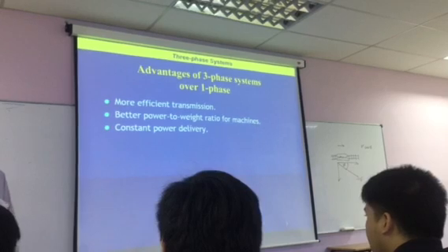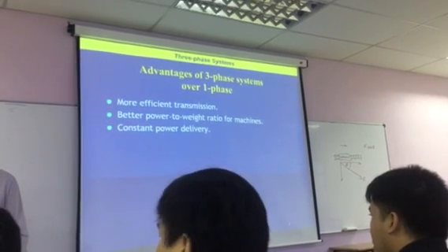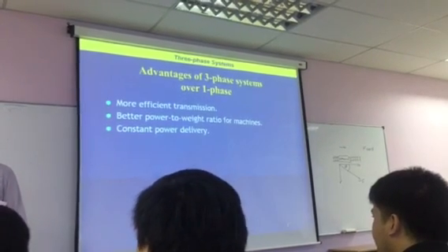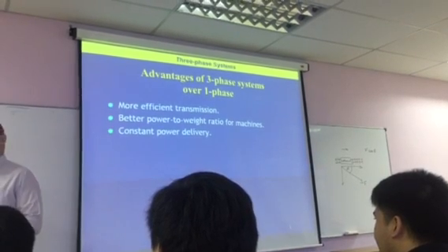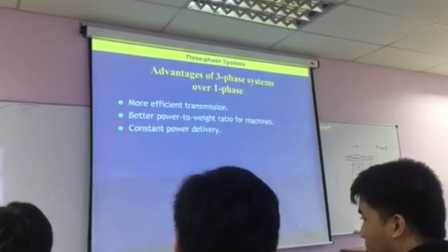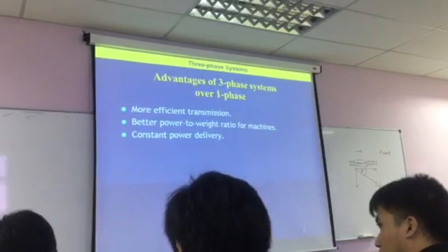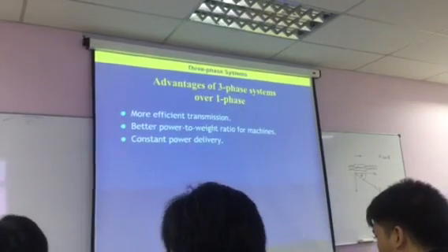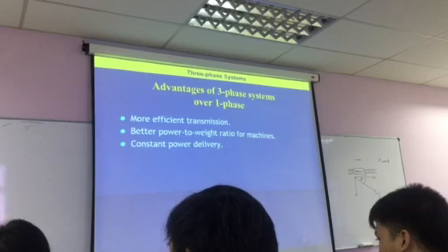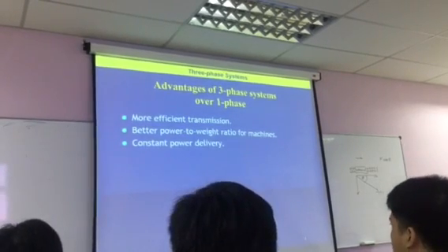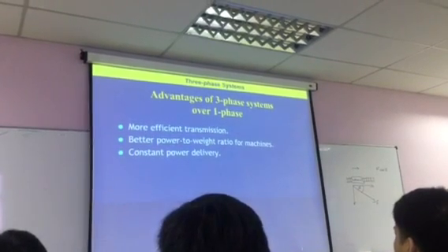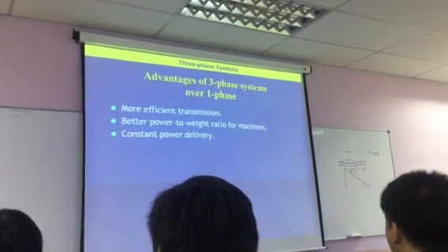The colours changed in about 2009 in Malaysia, because it was the old RGB, and it's now grey, black, and I have it on a piece of paper. The reason the colours are important is when you're connecting equipment to three-phase, because if you don't connect it correctly, it will either not work at all or work in reverse. Which can cause some problems. Some installers I know had a system where instead of sucking things, it blew things, and it caused a lot of problems. So that is something to be very careful of.